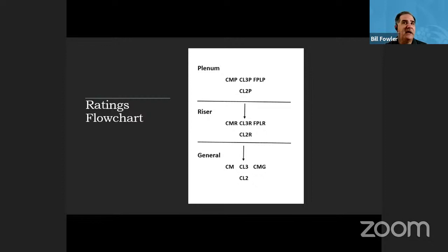But in most commercial spaces, you're going to see a plenum used. And then in the riser, because it's a little bit cheaper than the plenum rating because of the jacketing compounds that we have to use. You'll see that in riser application, a little bit cheaper cable, less expensive. I won't say cheaper, just less expensive because of the jacketing. And then you get in general purpose.